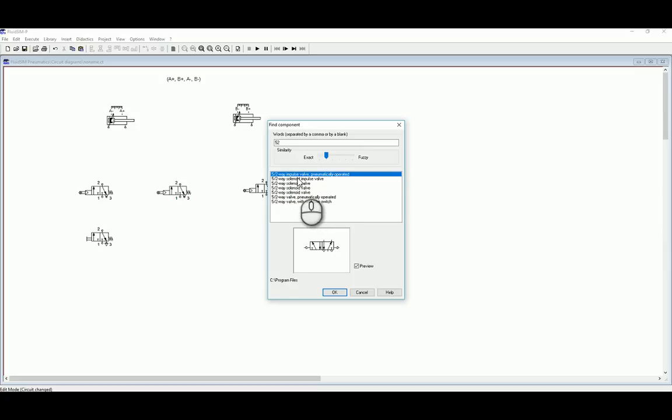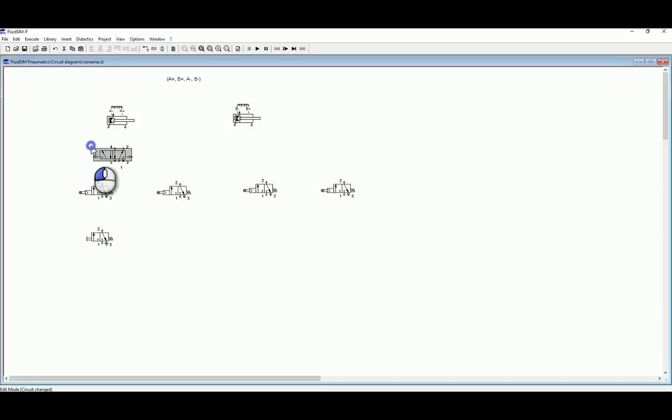So it's the first one that comes up. It's an impulse valve. They've also got spring return valves and D10 switches, which is the sort of rotary switch activation. So place into your particular circuit these 2 components, copy and paste the second one in.